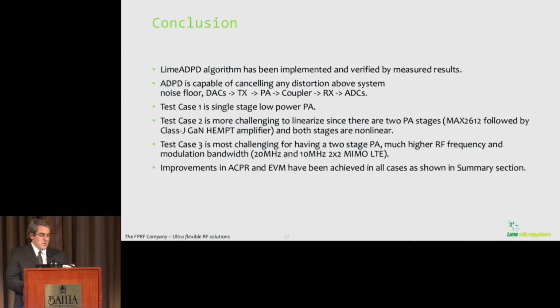So our Lime ADPD algorithm has been implemented and verified by measured results. I must emphasize that it is capable to remove any distortion above system noise floor: DAC, TX, PA, coupler, RX, and ADCs. So we have 3 test cases covering different amplifiers, different carrier frequencies, and also different modulations. And for all cases, we achieved significant improvement in both EVM and ACPR.